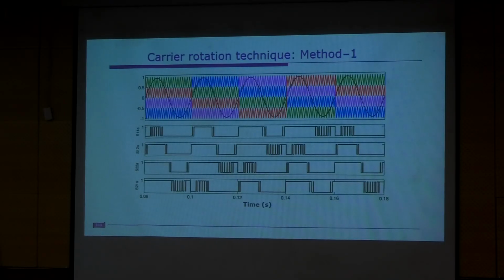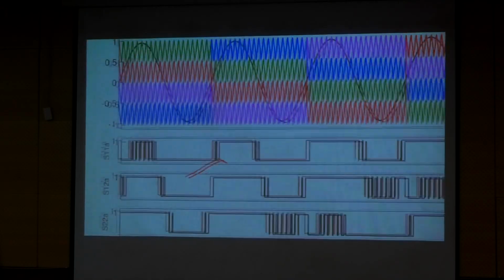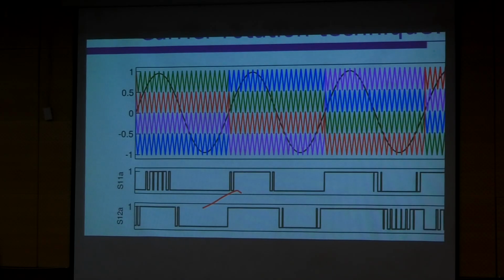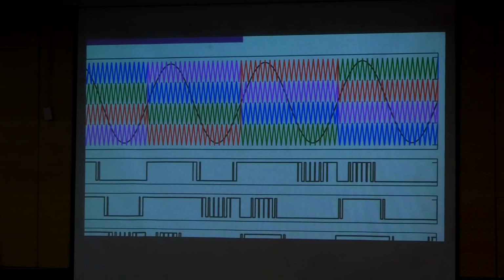So there are some methods, same level-shift PWM technique. We can still transpose the carriers. Let us assume that this is a carrier transposition. If you see, there are different levels, for different cycles, 4 cycles or 5 cycles here. In the first cycle, what is the change you observe? The carrier is changing its position. Earlier it is in one position, now it is changed to two, and in the next sequence it is changed to 4, 5, and at the fifth cycle again it comes to the first position.